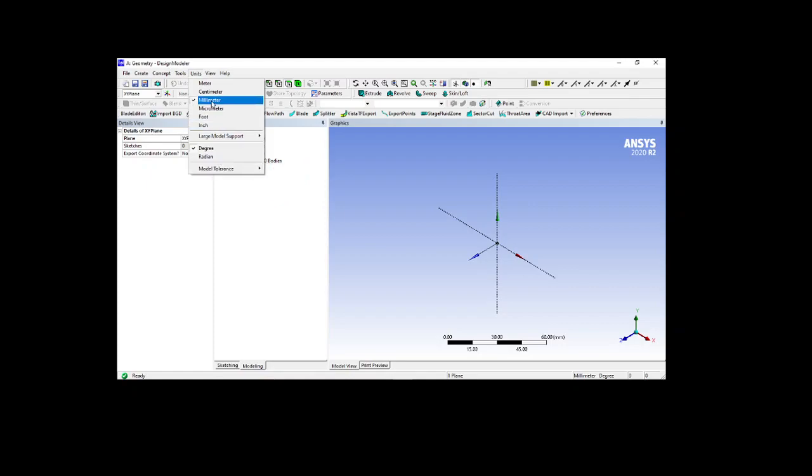If your measurement is small, meaning you are creating micro geometries or macro geometries, then you will set this to tight. If you are creating meter-scale, huge geometries, then you can set it to loose or normal. Next, this is the model support, it may not be helpful for you, so we will discuss it later.